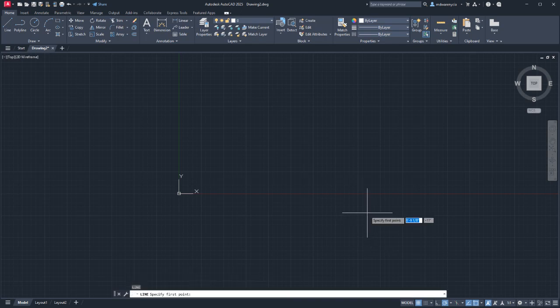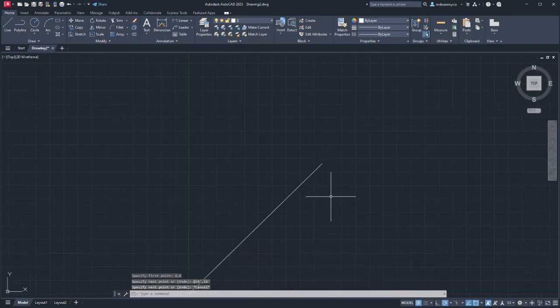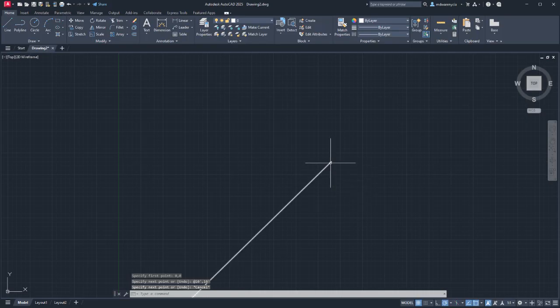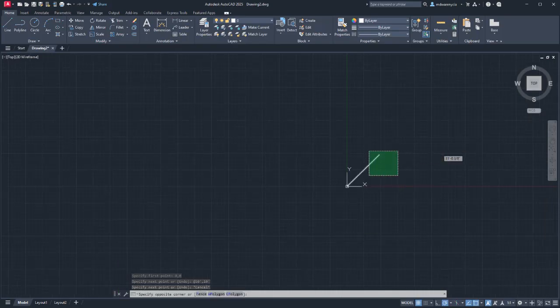You can also do specific points. Again, you're generally not going to be doing manual entry like this, but I want to make sure you know you can. So I can go 0, 0, enter, and then 10 feet, comma, 10 feet, and that will draw that up at the 10-foot point right there. All right. So there are different ways that you can draw.